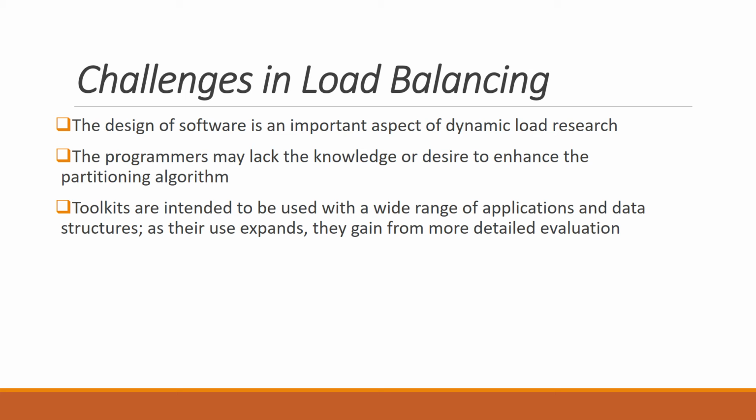In parallel simulations, task scheduling, the grouping of work to process units, is very critical. It improves application performance by minimizing processor idle time and interprocessor communication. Load balancing may be employed as a preprocessor in use with constant workloads. Other implementations like adaptive finite element analysis have unpredictable or changing workloads. These programs demand highly dynamic load balancers that modify the partitioning as computation progresses.